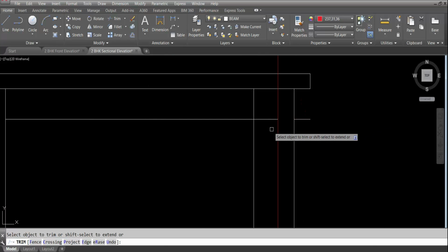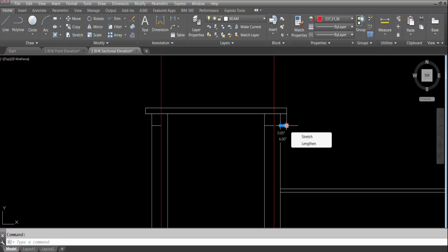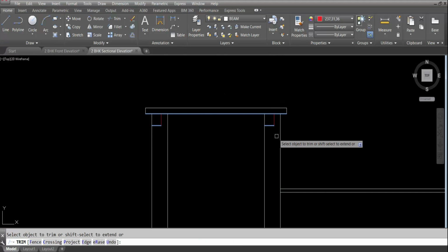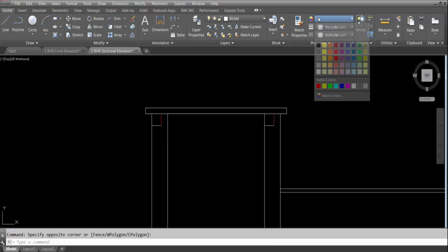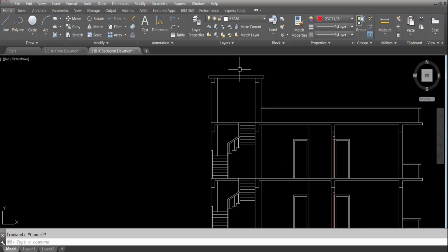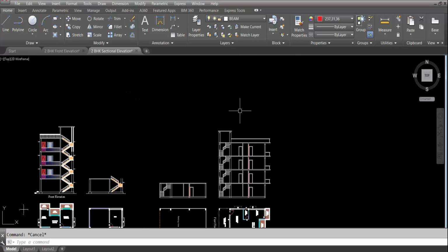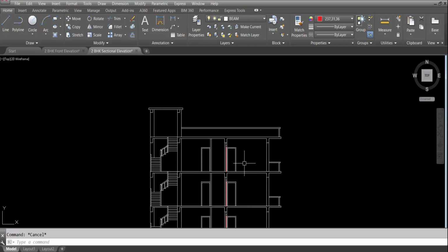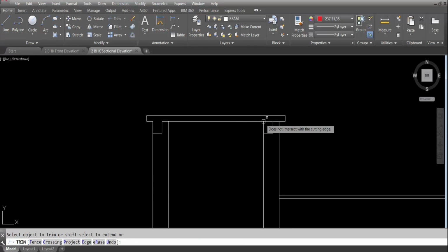This is 9 inch by 10 inch. Okay, 9 inch by 10 inch. Trim extra lines. Select staircase headroom beam 9 inch by 10 inch. So trim all the extra lines here, here, here, and here. This is the beam. Now select, make the layer as beam layer by layer. Okay. This is the beam for staircase headroom 9 inch by 10 inch. Other beams 9 inch by 15 inch. And trim the roof slab. Staircase headroom roof slab also we have to trim. Trim here and trim here.